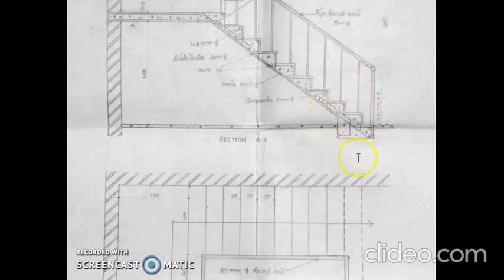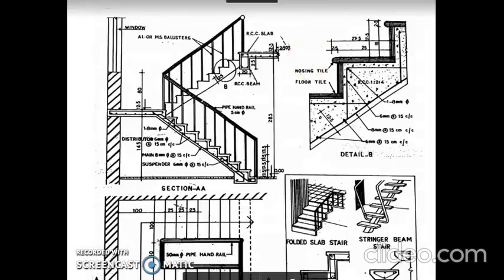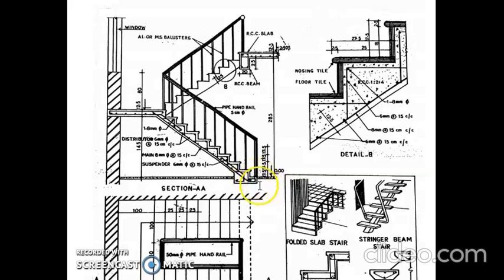And also this part here, there is a foundation part, so the foundation width should be provided. We can use this projection width as 5 centimeter. This projection, from the first rise, this width can be taken as 5 centimeter. Then this depth can be taken as 5 centimeter. And again, extend this portion.